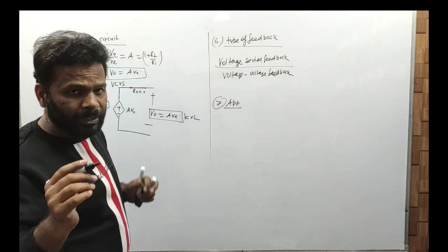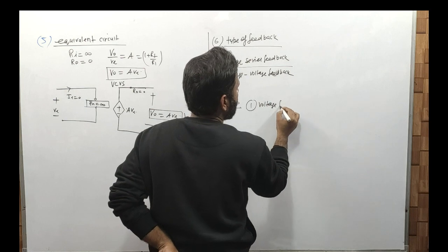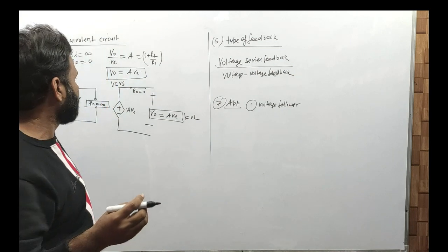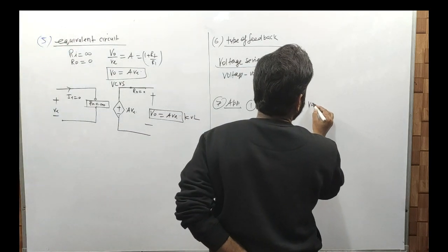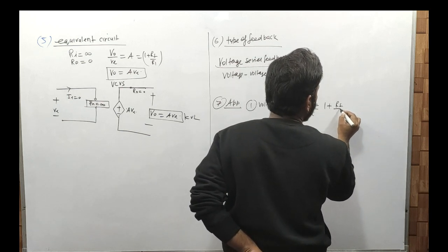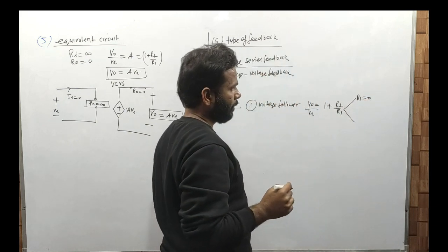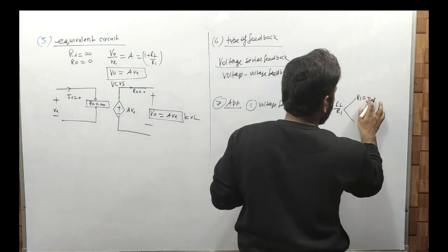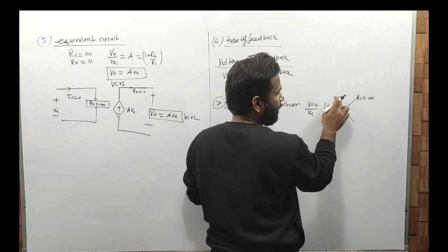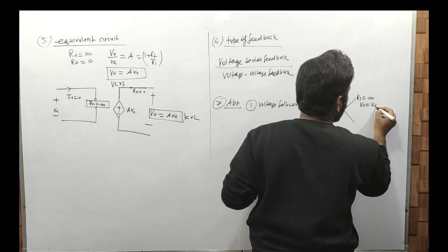Now the first application of non-inverting op amp is what? Voltage follower. Now voltage follower क्या चीज होती है, शॉर्ट में बता देता हूँ, उसको हम अलग से लेक्चर में भी कवर अप करेंगे। सो अगर हम बात करें, V नॉट अपॉन VI इक्वल टू 1 प्लस RF अपॉन R1। नाउ if you take R1 as infinite, then what happens? Then something by infinite is 0, so 1 plus 0 is 1, so the output is just equal to VI.